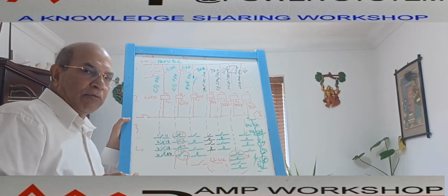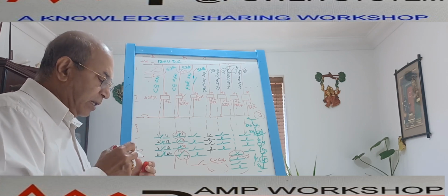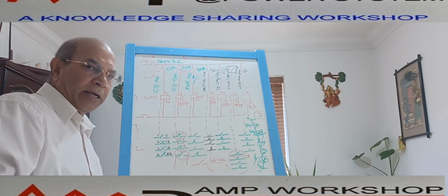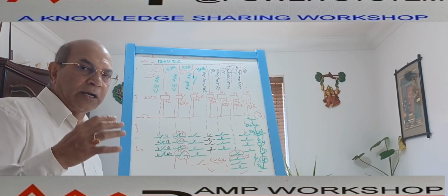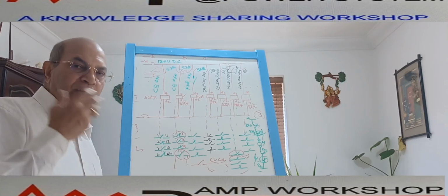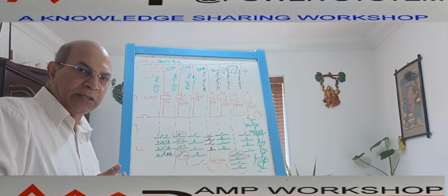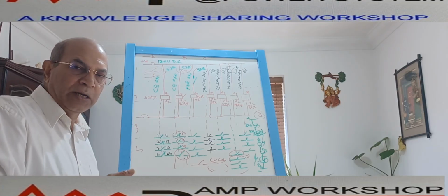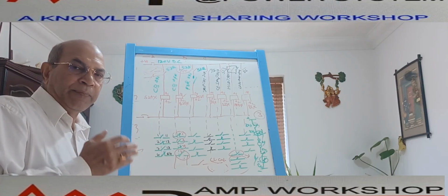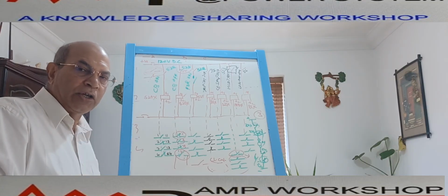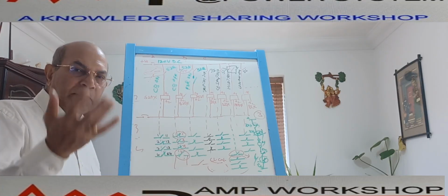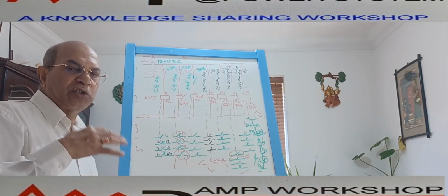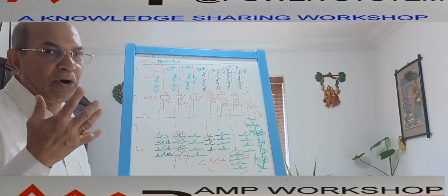Then the lockout relay, which we said is in the tripping circuit. This lockout relay has multiple contacts, but still, because the lockout relay contact is used in various circuits: the tripping circuit is required, the closing circuit is required, local remote indication purpose is required. Then this lockout relay contact is also required for remote and tripping also. So the lockout relay contact has multiple applications. Even with 6 contacts, 3NO 3NC, that may not be adequate.